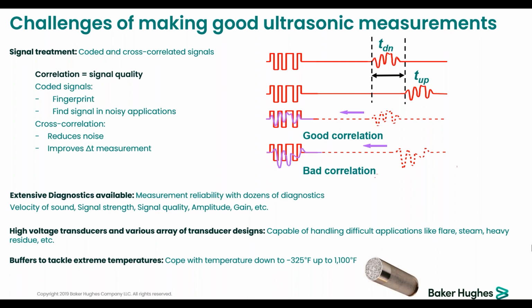So the signal-to-noise ratio is improved when we have such a setup. And when we put the transducers on the outside so that they can be easily replaced without interrupting the flow, it also gets a proper signal propagating into the fluid. So these are the few things that we have developed through the years at Panametrics.